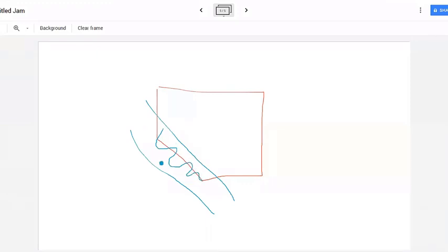But the problem is we need to know the tx and ty component of it. If this is your surface and this is your tolerance range, I need to know how much it can go in horizontal and how much it can go in vertical. That's why we need to do a small trigonometric calculation to get the variation of it.